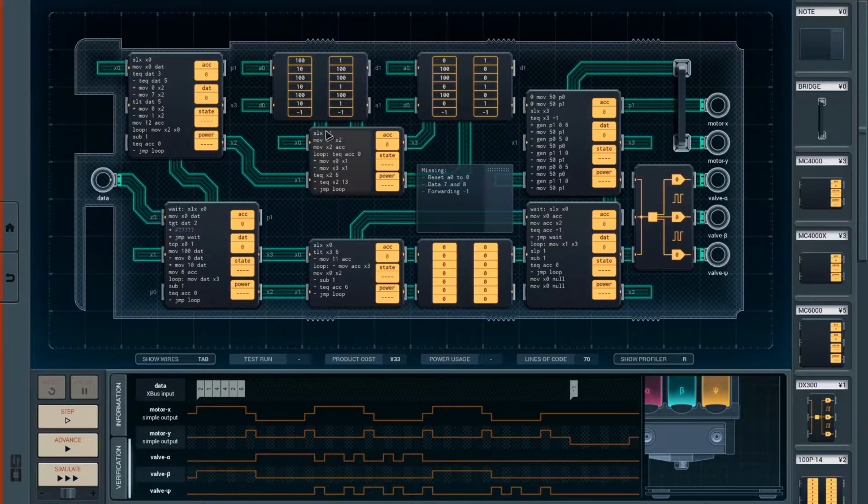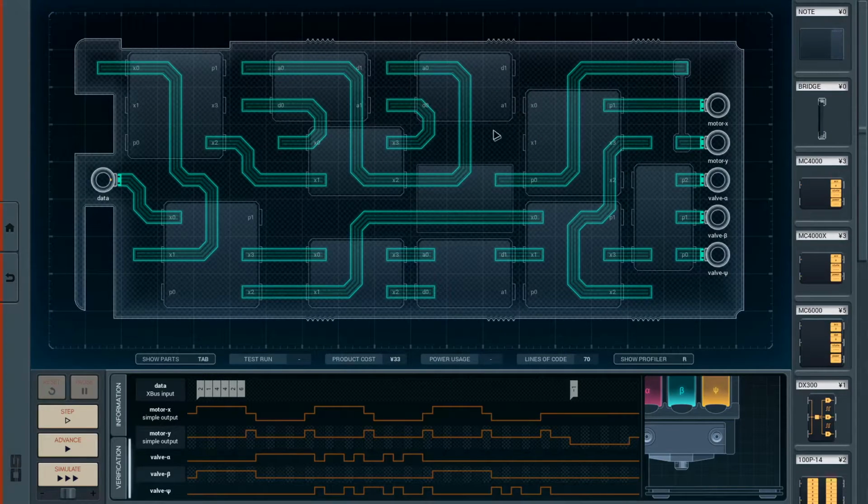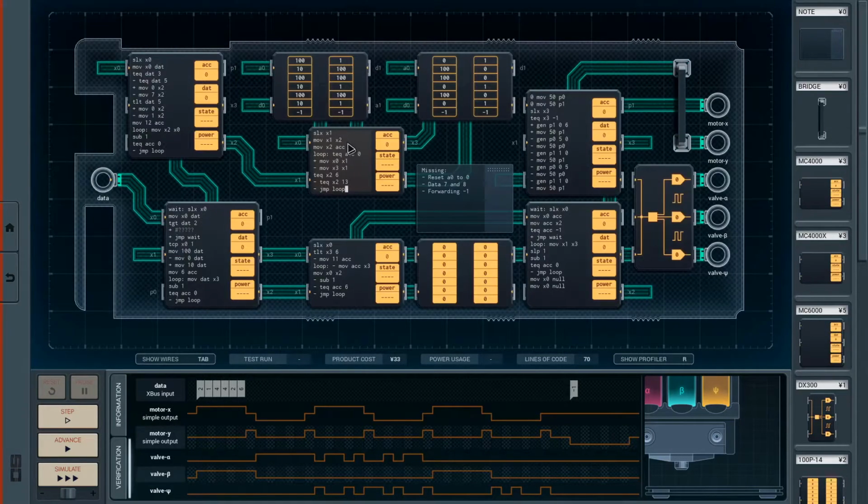No, let's see. So this sends something to it that gets set to the address line of both of those. Those are just wired together. Then bank selection determines which of these two it reads from. So basically I send two numbers that determine which of those I'm going to get. And then it just sends it back.